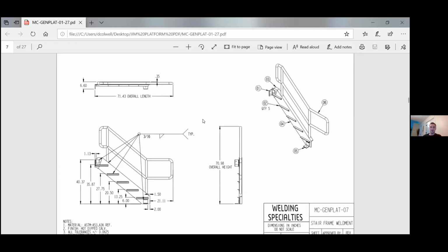Okay, so this is a good example of an assembly drawing. What we've seen so far, in fact, we kind of skipped this piece here, but we saw piece 1 and piece 2 and piece 3 and piece 4, and now we're bringing them all together into an assembly. And so these 01, 02, 03s match the part numbers. This is 07. 07 is a sub-assembly. So 07 is made up of 01 through 06. That's not the way you have to do it, but it's the way we do it at Tandem Lock, and it makes sense, and it usually works pretty well.